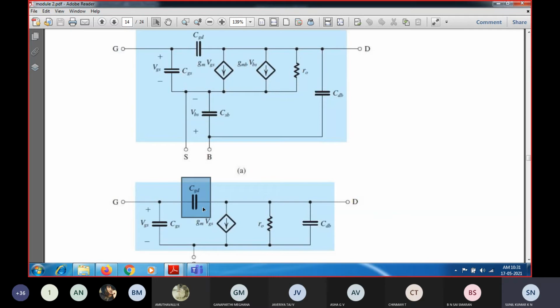So when you employ negative feedback, we have seen common source with source resistance. The source resistance was acting like a negative feedback resistor action, because of which the gain was reducing by a factor of 1 plus gm into RS. So here also, any feedback is going to be negative feedback, so obviously the gain is going to reduce at higher frequency because of this MOSFET capacitance.